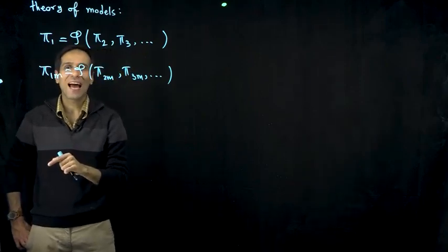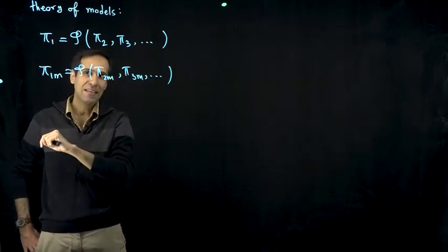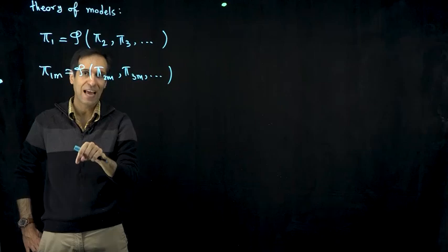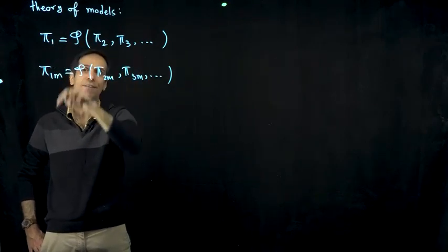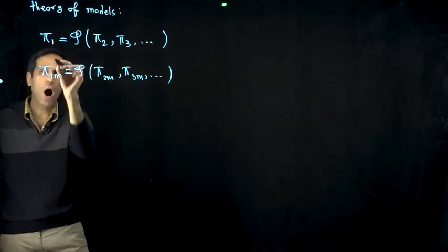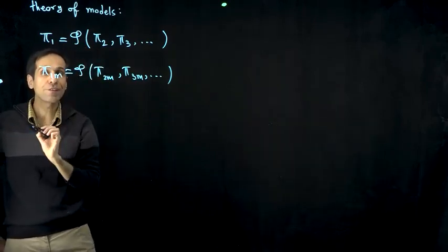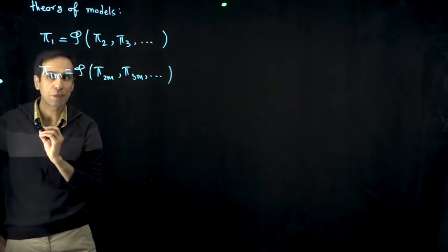To make sure that this model exactly behaves and predicts the behavior of the first one, the prototype, all corresponding dimensionless parameters should be identical.